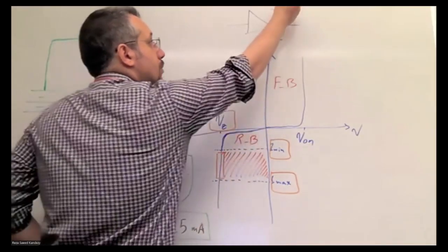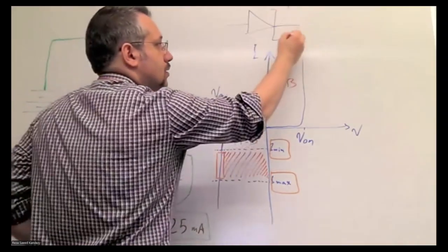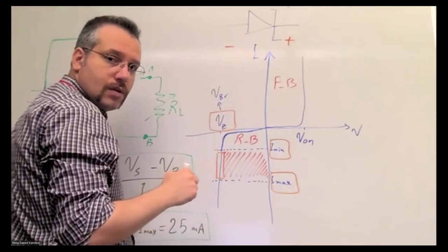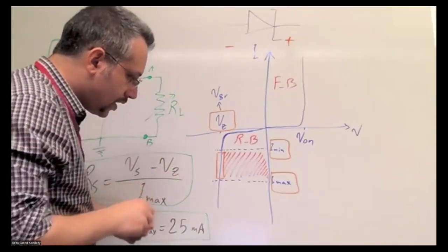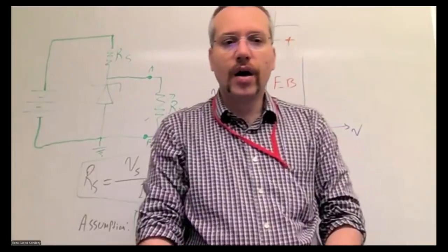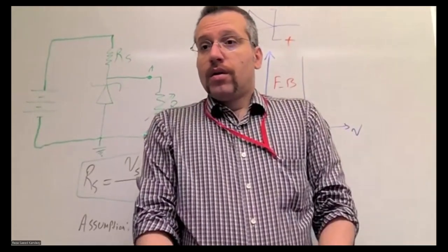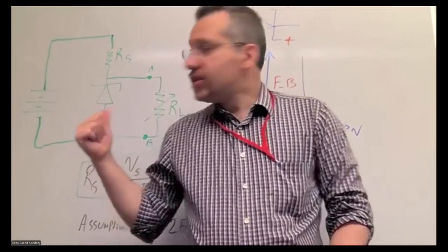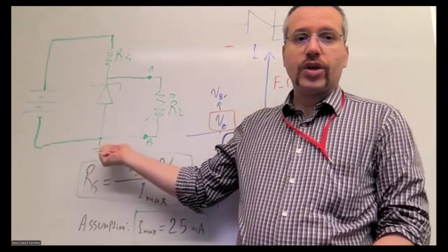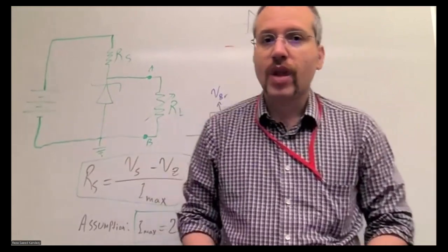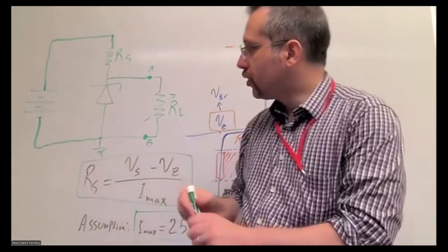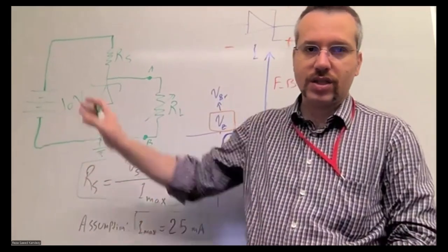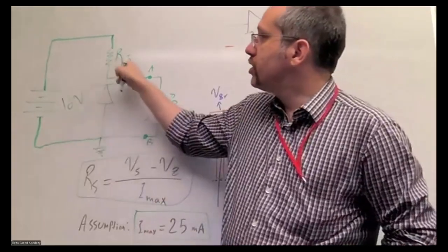So higher potential is going to be at this part. Oh, sorry, at this part. And the lower potential is going to be at the anode. Okay, so it's the opposite way of a general diode in our circuit. Now, this is a circuit for a Zener diode voltage regulator. Here we have a voltage source equal to 10 volts in our example. Okay, this is a DC source, and it's connected to a series resistor RS.